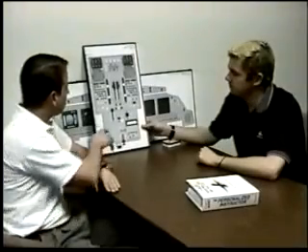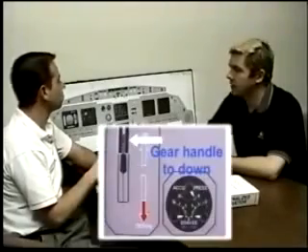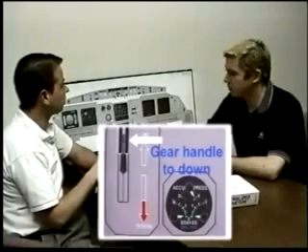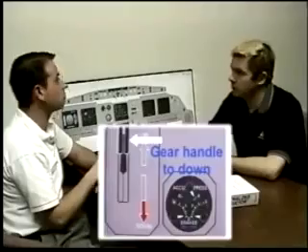Okay, after cranking it 3 times, what would you do to not get some of the gear warnings? I'm going to go ahead and put the gear handle down. Match the gear handle with the gear. Another idiosyncrasy with cranking the gear down is that I'm going to lose the nose wheel steering.